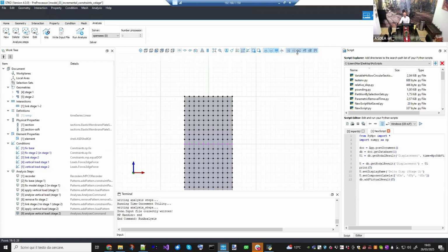So typically what I did before was to do an eigenvalue analysis, and in that way you can see if there is a very huge period or directly an instability. Oh, and just remember, from version 3.7, because if you try to use this code with a previous version, it will not work. It will just tell you that the automatic constraint handler is not available in OpenSees. So just download or compile the latest version.